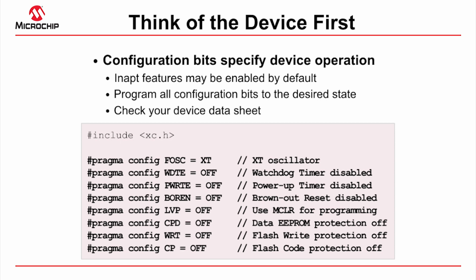The device debug mode is set automatically by MPLAB IDE. The configuration bit settings you need will almost certainly be different to this. Check your device datasheet to see what settings are available on your device and how they work. Check your compiler's user's guide for information on how you set the configuration bits and the names of the settings. If your code runs on the simulator, but not on an actual part, then the configuration bit settings are the first things you should check.